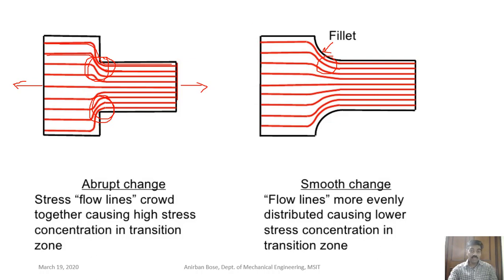But again, if you compare in this particular component far away from this fillet, that means in this region or in this region, you can see that the concentration of the flow lines is higher. That means with respect to this region or this region, there are stress risers present over here, and that is why stress concentrations are present. Okay, so we cannot totally ignore the stress concentration effects when we are going to design.